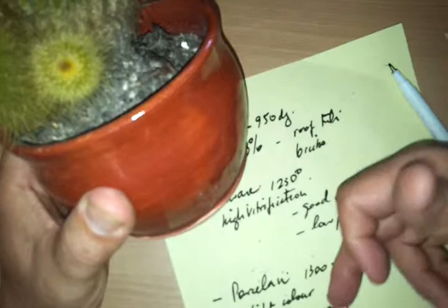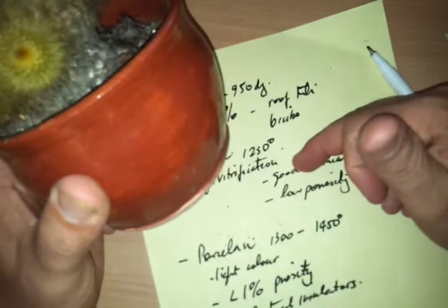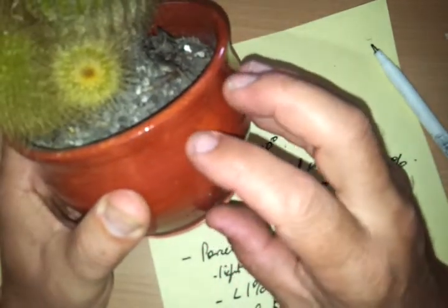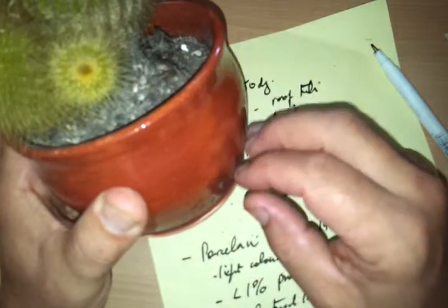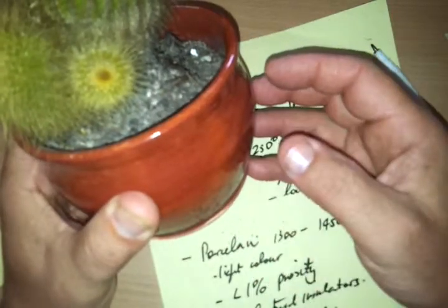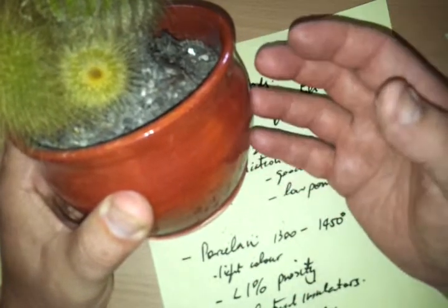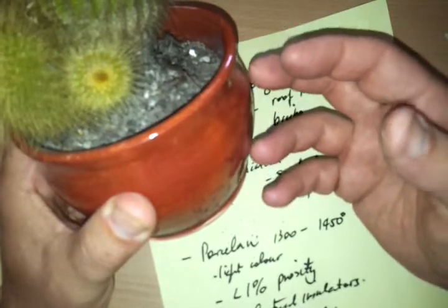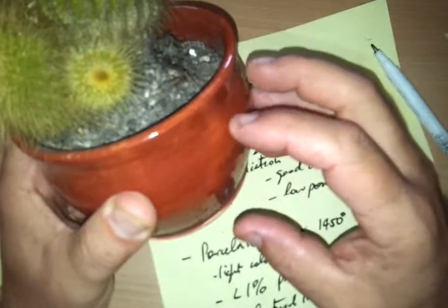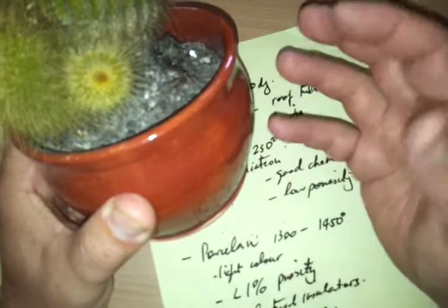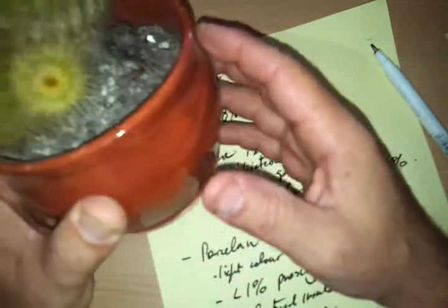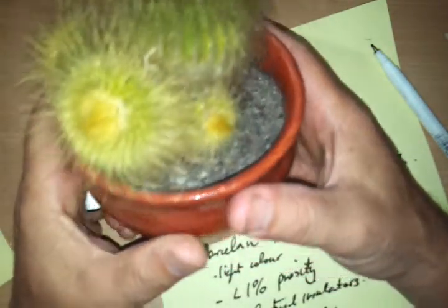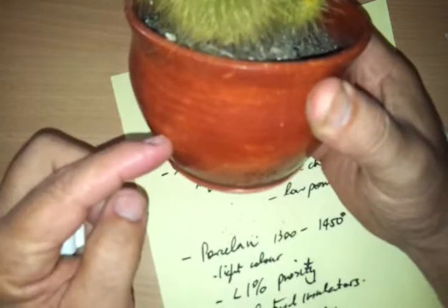Fire it up to the temperatures that are required for vitrification, and then you get an outer form of vitrified glassy called a glaze, and inside you have the earthenware. And that's probably a cheaper version than trying to create something like this out of porcelain, and also retain some of the material properties of the earthenware, which may be desirable for you. For example, you might want some porosity down the bottom, or you might want it to be able to breathe a little bit, but that's a use of glazing.